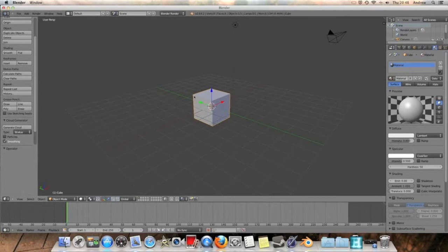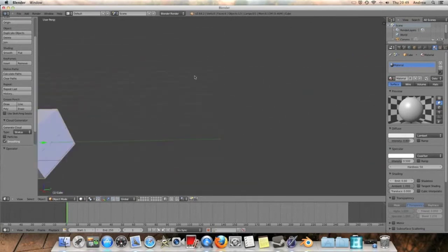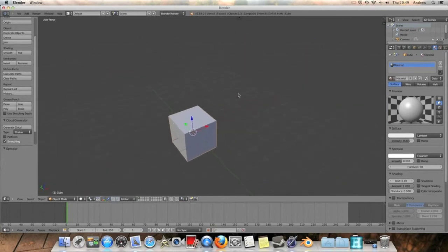So yeah, middle mouse button to move around the screen, and if we press Shift and the middle mouse button, we also move the screen like that in 3D space. And if we move all the way over here and press the middle mouse button again, we'll rotate roughly around where we just moved. So let's see, move over here, and we rotate around there when we just use the middle mouse button. And obviously you get more used to that as you get around later.